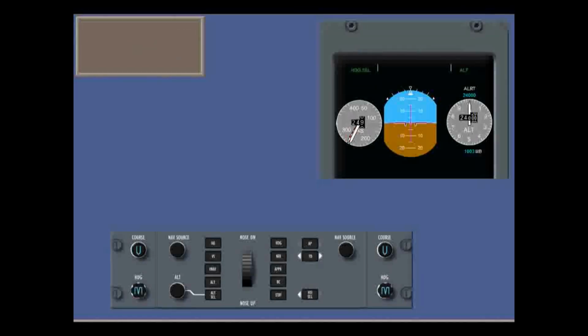But with the autopilot not engaged, touch the standby button again. The autopilot stays disengaged. Flight director modes are cancelled, but this time the command bars are removed. So standby has no effect on autopilot or yaw damper engagement. However, as well as clearing modes, it also clears any flight director abnormal messages on the flight mode annunciator.